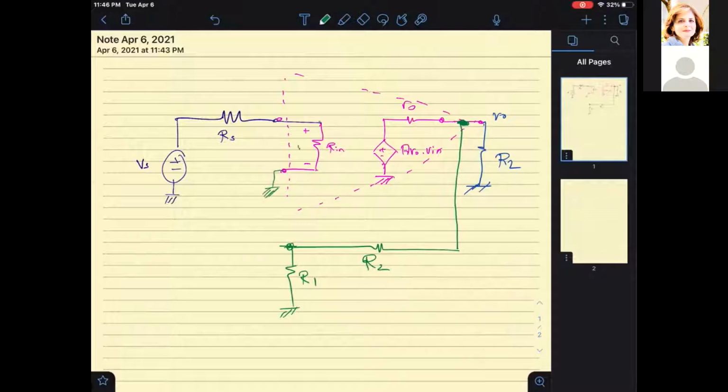Okay, so in real life, ideally, we would have had ground, would have had the signal sent to Vn, and would have amplified the signal and fed it to the output. With the feedback now, we will really sense the output and apply some feedback component, some beta times VO, into the terminal such that now, if I call this node Vf, I will have minus Vs plus Vn plus Vf equal to 0.